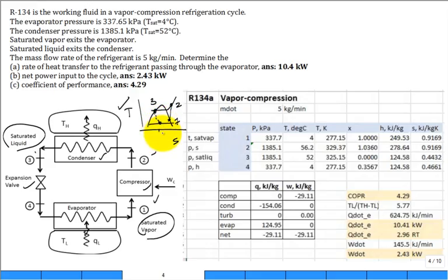Why do we put a dashed line, not a solid line between 3 and 4? Because the area under that line does not mean anything about the heat transfer. Where if it would have been a reversible path, yeah, but it's irreversible. Nothing to do with the area under the curve. So that's the convention to use dashed lines when it's irreversible.